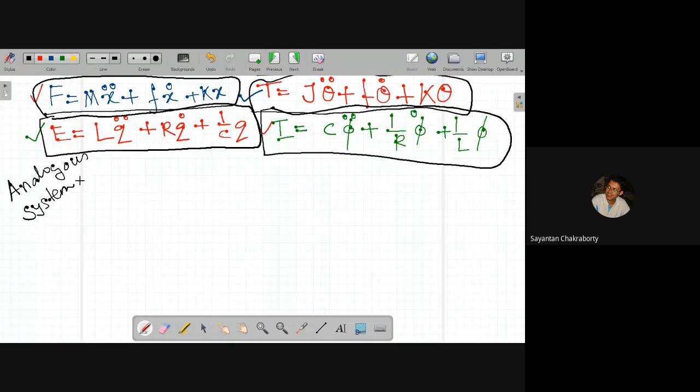On the other hand, if you can have a mathematical model of the system, say it's described by a second order differential equation, then you can simulate the similar response or the similar behavior by a combination of series RLC or parallel RLC circuit. The values of L, R, and C will be a function of M, F, and K of the system. And whatever the values that come up, you can suitably choose your L, R, and C values based on your calculations. That electrical equivalent of the mechanical system will be sufficient to study the dynamic behavior of the system.